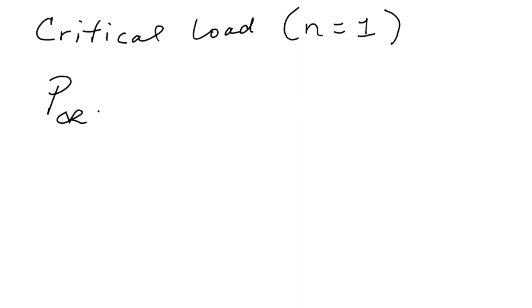Let's call this the critical load, which really just means n equal to 1. So in that case, P critical is just pi squared EI over L squared.